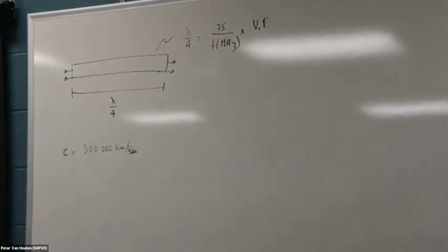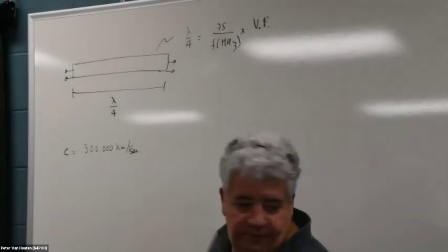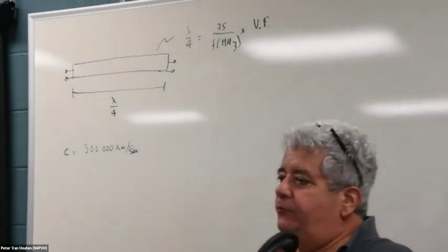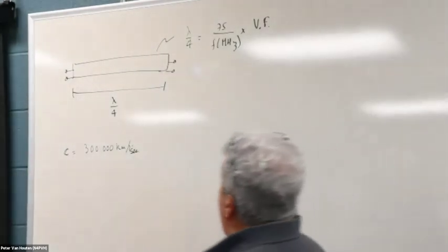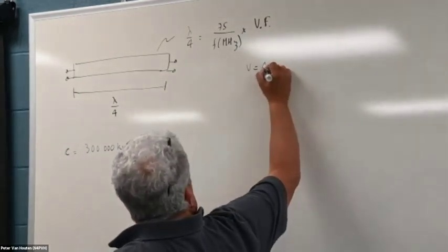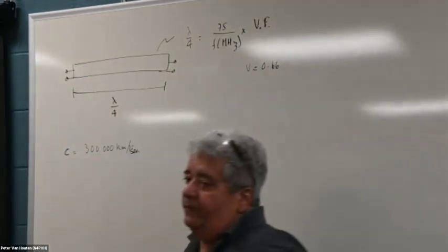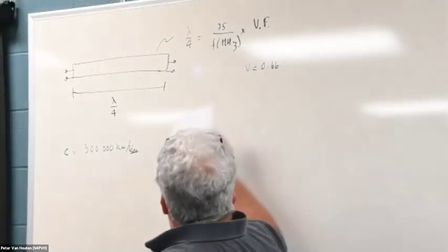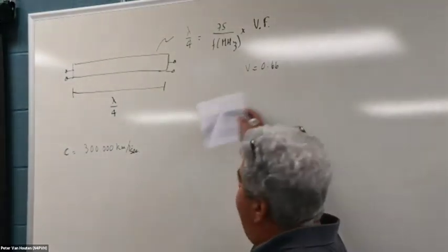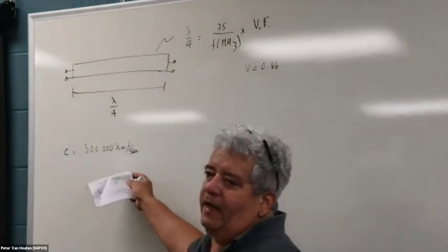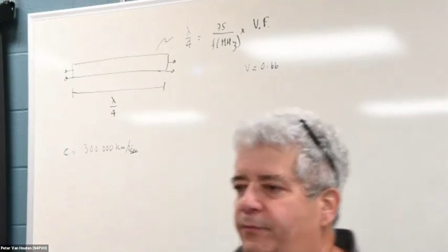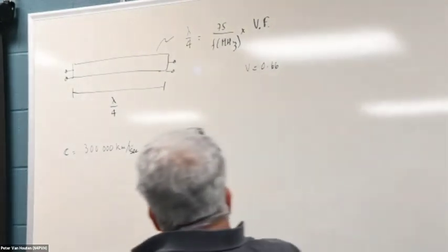Okay. So on the coaxial cable, there's a velocity factor, and a typical one, for example, this cable that I have here, which is an RG213, the velocity factor is 0.66, which means that the waves inside the coaxial cable are traveling at 66% the full velocity of the light in free space or in the vacuum out there in the outer space. So this is the formula.